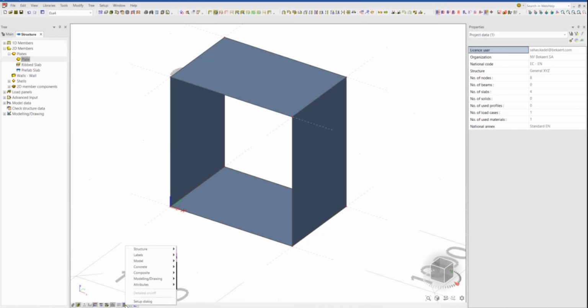After that, I'll just try to check the orientations of my local axis. So in case of a box culvert in SCIA, the thumb rule that I follow for local axis is I always try to orient the local z axis outwards, and for the base inwards.